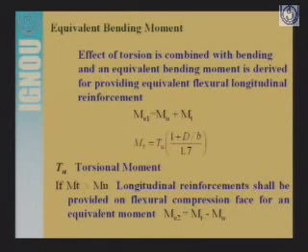Mu you know, that is the bending moment normally coming to the section. Here Mt is calculated as Tu into (1 plus D by b) upon 1.7. This formula is given in the code. So you can calculate Mt with this formula and reach the equivalent bending moment value.